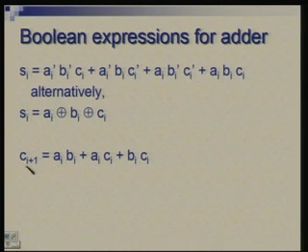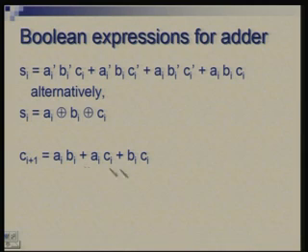Okay. Carry, on the other hand, is 1 when you have 2 or more inputs as 1. So either they could be Ai and Bi, Ai or Ci and Bi, or these two, or these two. The case of all 3 being ones is actually covered by this. If you are familiar with Karnaugh map, if you have done this in your digital electronics, you would know how to get this systematically by drawing a Karnaugh map and finding a minimal representation in a sum of product form.